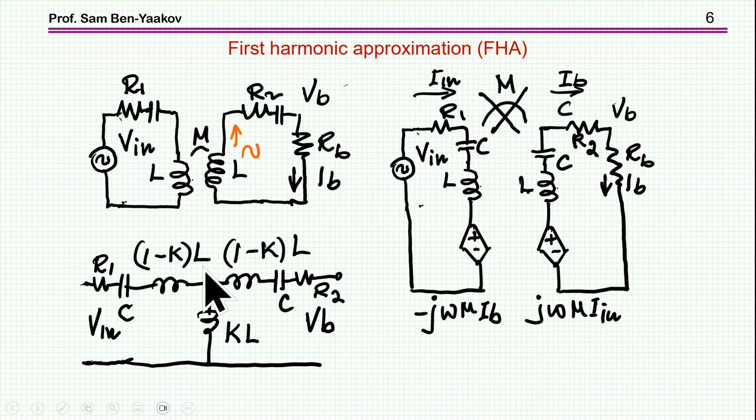So you can develop here very high voltage, actually higher than the input. And then if the load resistance is very small, let's say it's a short here, you see that you can actually have two resonances here. You have one between this and the rest of the circuit, and then between this and another part of the circuit. So you might have two resonances, and in fact you do have it, and I'll show it later on.